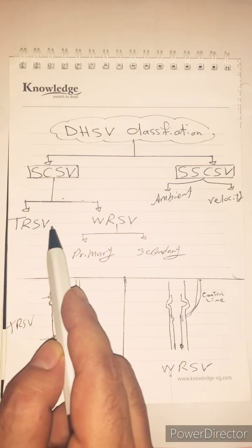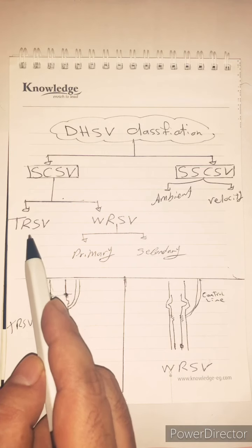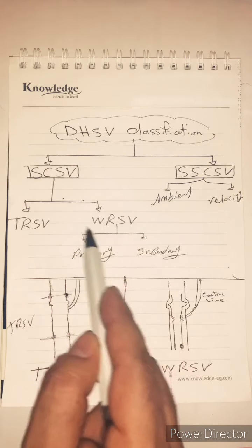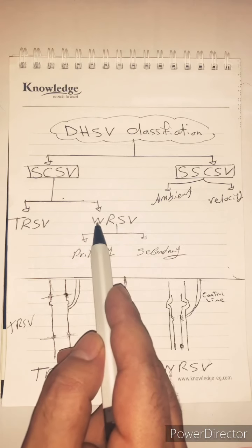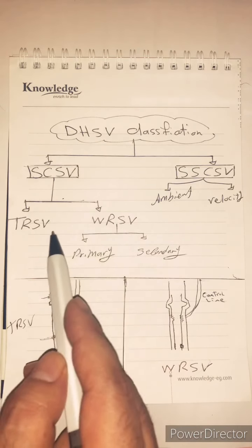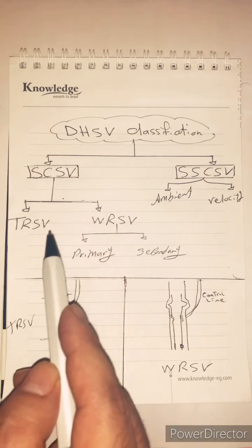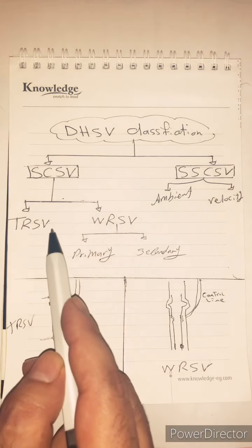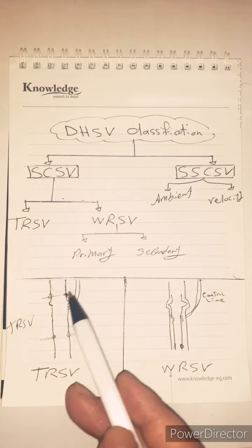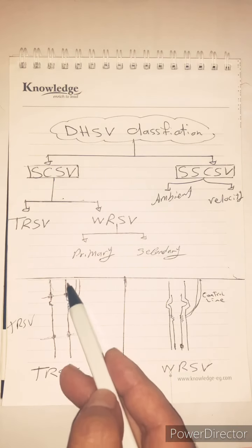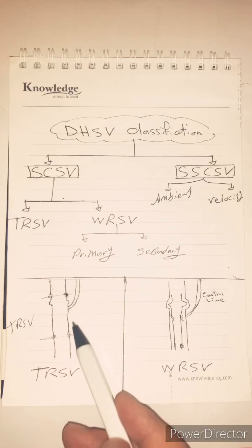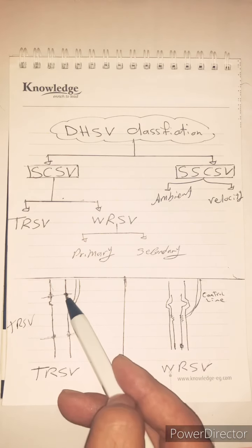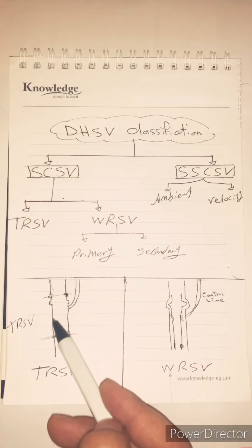Tubing retrievable safety valve is the most common in today's operations, but wireline retrievable safety valve, primary type, was used in the past. Nowadays, wireline or completion engineers recommend using a tubing retrievable safety valve. Why? Because it can be set with the completion as an integral part of the completion tubing. That means there is no restriction in the flow path. Okay?